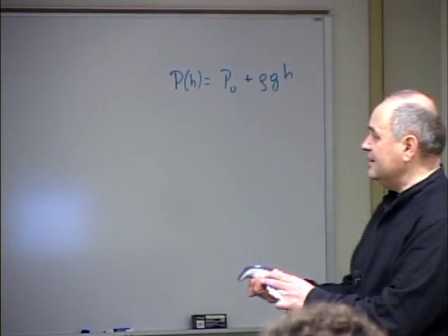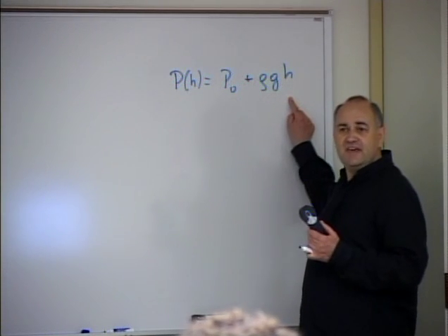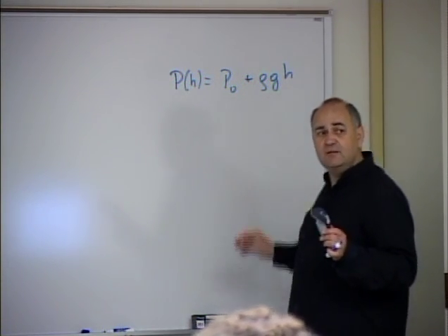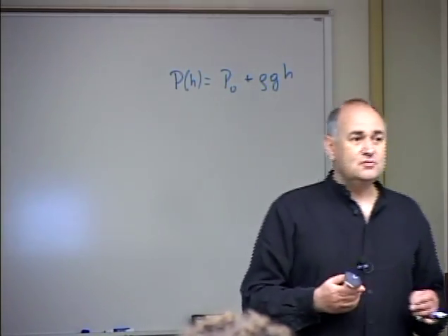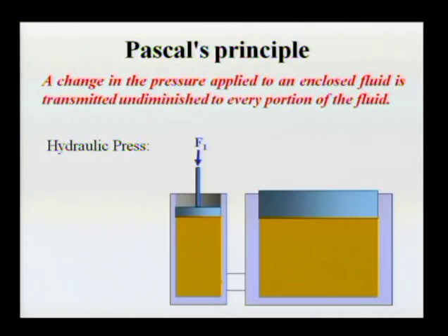Think about it now. You have a certain distribution of pressure with, let's say, zero force. Now I will push it. How will the pressure increase? Is it going to increase more at the bottom than at the top? More at the top than at the bottom, or equally? Equally, correct. For a particular depth, the pressure is not going to be uniform, so pressures will be different, but the changes in pressure are going to be equal everywhere.